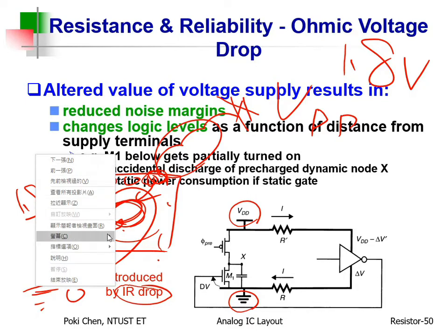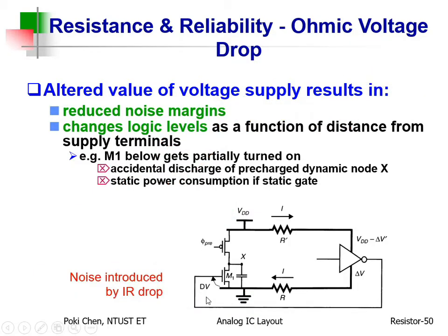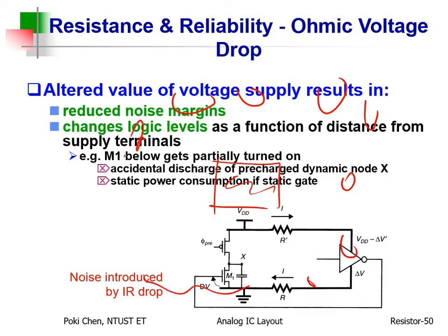If you have had your chips taped out, you will know what I'm talking about. After you finish the layout for your core circuit, you have a lot of I/O pads, right? Then for your VDD, ground and I/O pins, I'm talking about the routing from your core circuit to the VDD and ground pads.